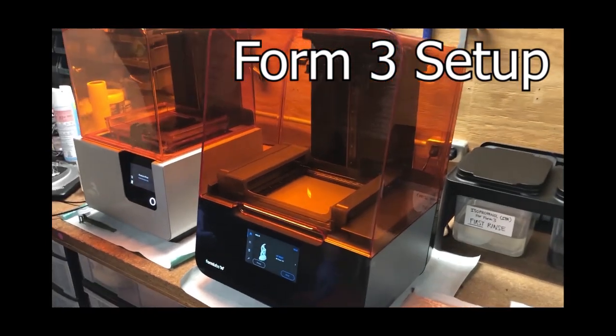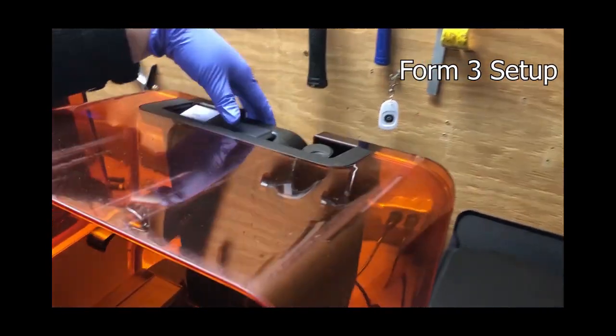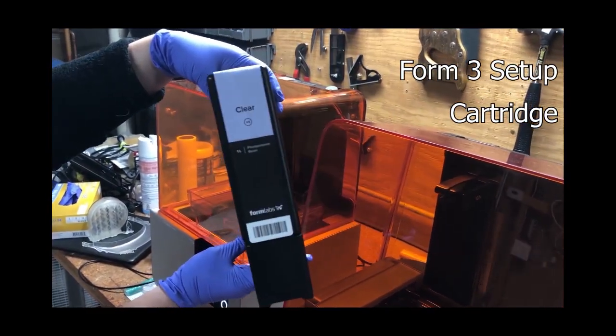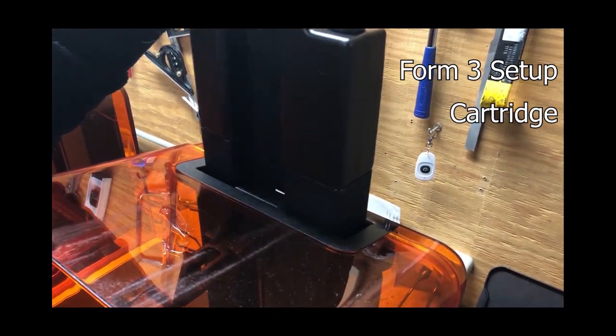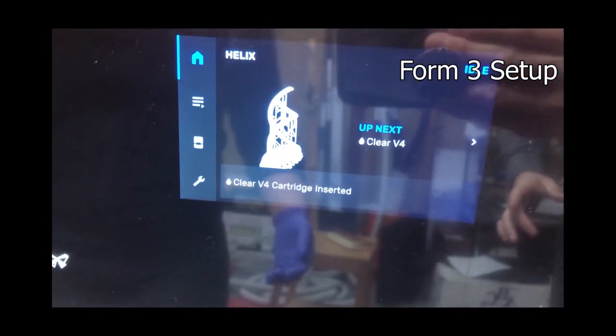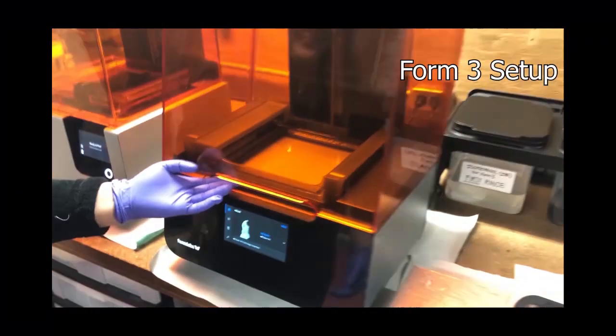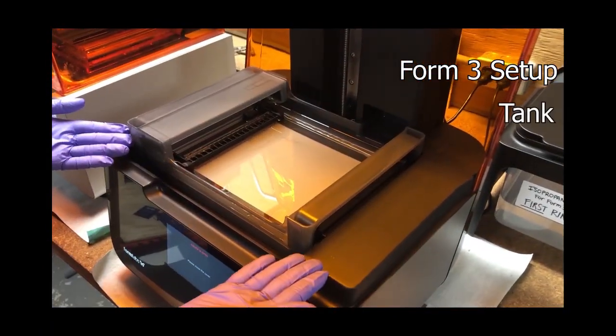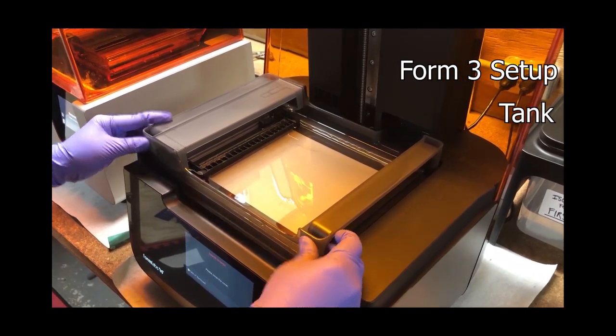For the Form 3 setup, I have a very quick video to show you guys. There you go, and hopefully the quality will be okay. Here I'm showing you the cartridge. That's how the cartridge looks. We have the clear resin, and it has a nice handle that you can slide back there. Make sure the printer registers that you inserted a new cartridge. That's very important. Otherwise, there's probably something wrong with the sensor.